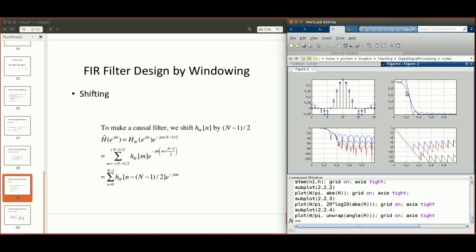Again, there's some slight difference if you plot them in the linear scale, but in the log scale, the difference is much more obvious. The Hamming window is something that's kind of between the red curve and the blue curve. That's the black curve here. Because the shape of the window is slightly different, you have some slight differences in the amplitude spectrum and also in the phase.